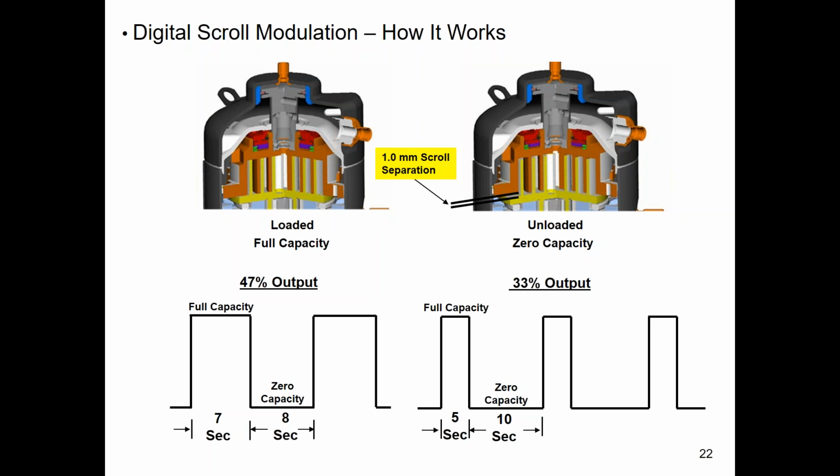We had, and this goes back multiple years, maybe as many as 8 to 10 years ago, on the 30 RB units, that joint breaking, but that was resolved by a different connection point. They had just too sharp of an angle on it. It was breaking, but that's been long rectified. So that's not a current issue if everything is normal. So I would say address the vibration, what's causing that, rather than doing something with the joint itself.